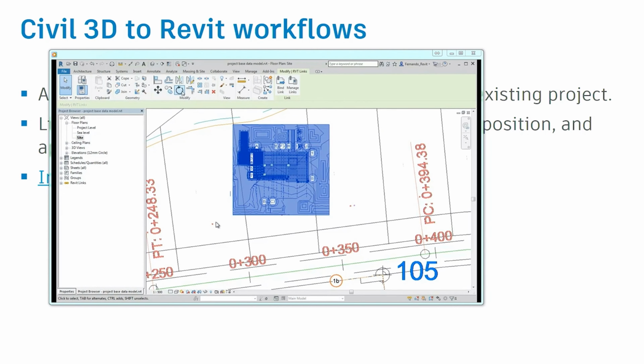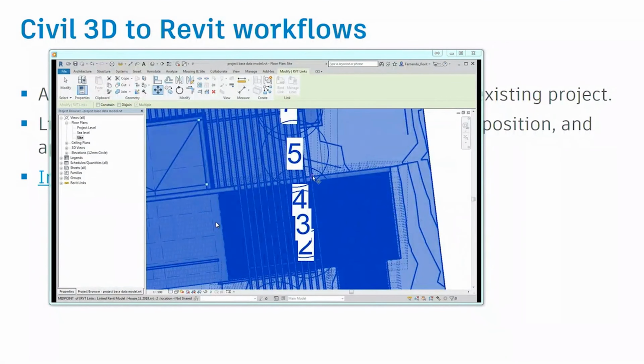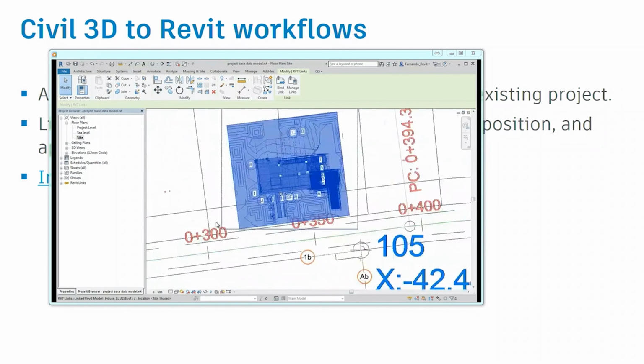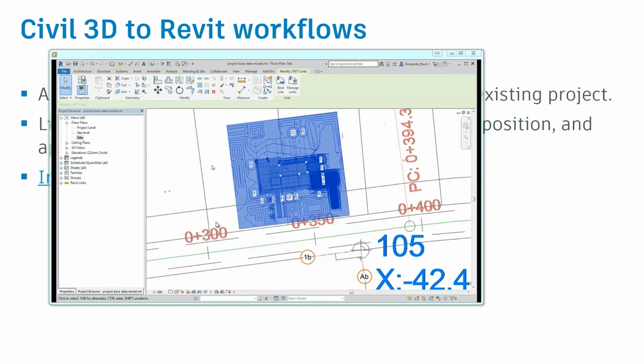Sometimes we can do it, but we need to be careful. Because in this case, as I used this model before, it had its own coordinate system. So you go to the site option, and you see more than one system there. We need to remove the old ones if we don't need them, or make current the actual one that we're going to push. So, okay, this is align, move, rotate, put where we want, change the elevation, create scope